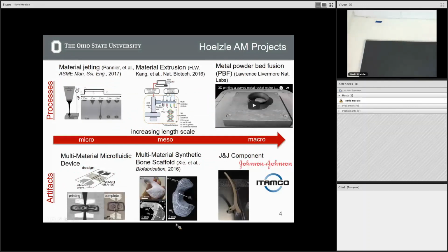This is a project where we looked at how you make this part, which is made of 316L stainless steel. We looked at basically the physics of making these parts, and basically distortion of this part as we print. That's something that we'll talk about extensively in this class: if you have a very thermally driven process, how that causes distortion in the part you're making. What you see here in this picture is this part that's being passed around when it was still on the build plate, and this is now taken off the build plate.